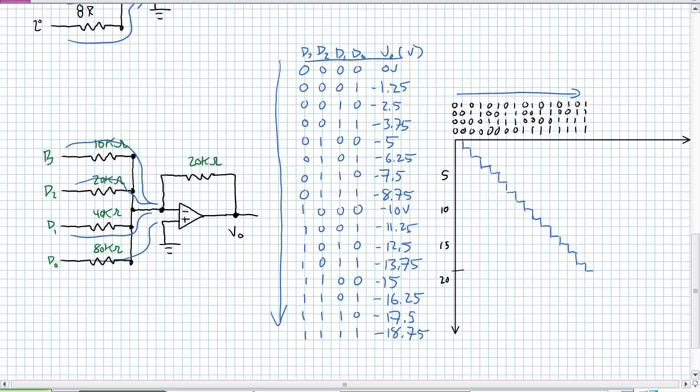Let's illustrate some non-monotonicity. Perhaps one of the bit positions is stuck in 0. Let's go ahead and see if you could figure out which bit position is causing it when I give you this graph here. So what I've done is here I've introduced an error in the conversion of this digital signal to our analog output here, and what I've got here is our expected value is that nice linear slope, that black value. However, what we're observing is this green stair-step waveform here for those individual combinations. Okay, so look at it and see if you could figure out which bit position is the problem.